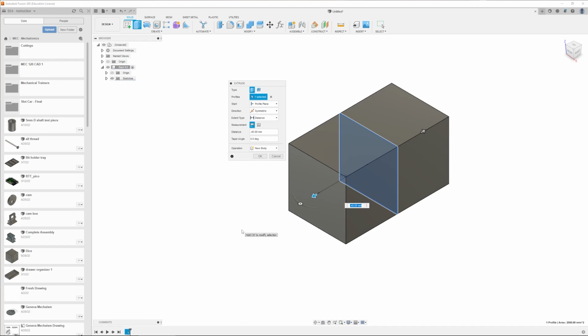I'm not going to need to go into detail about all of those particular cases, but as a general rule, if you intend to make a symmetric solid body in some fashion, choosing the symmetric extrusion method can be beneficial because it can allow you to take advantage of one of the base planes of the modeling space.